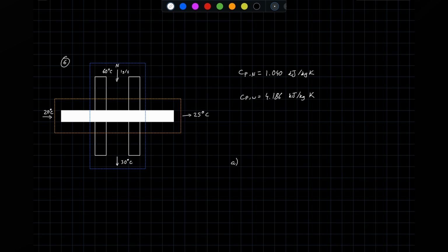water. Okay, for problems like this, the easiest thing you can do is work with the enthalpies. Basically, if we just focus on the blue system, your mass flow going into the pipe is also the exact same mass flow flowing out of the pipe, which means that if we look at our energy balance, we established already that there can be a heat flow, but there is no work flow.